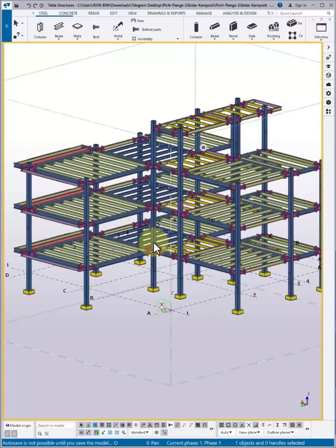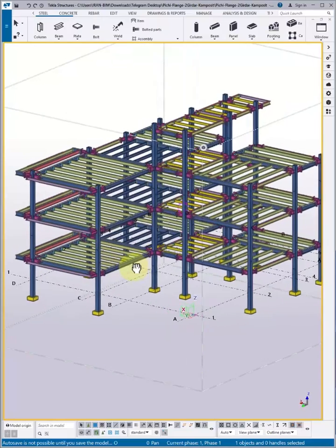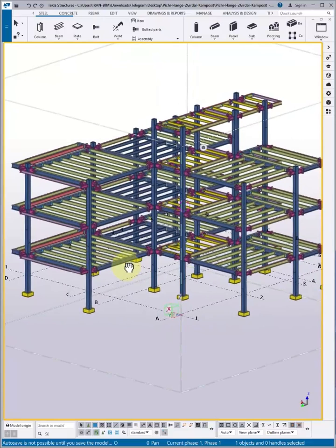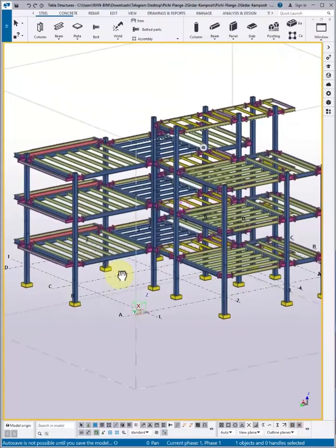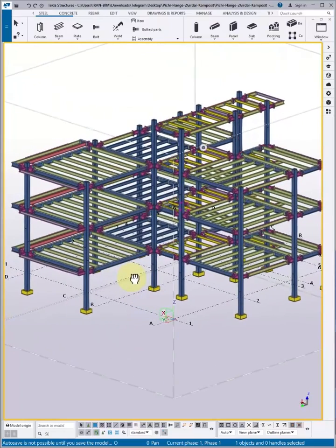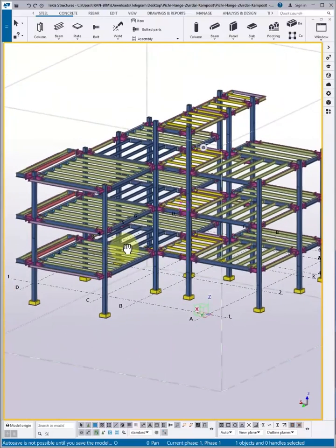I'm sure that you used to export your file as an IFC file type, since as you know, IFC is a file type which is accepted and supported by the software, so it lets you transfer your files among the software. But in this episode, I want to convert this Tekla model into Revit. So to do this, you are required to use Tekla integration.